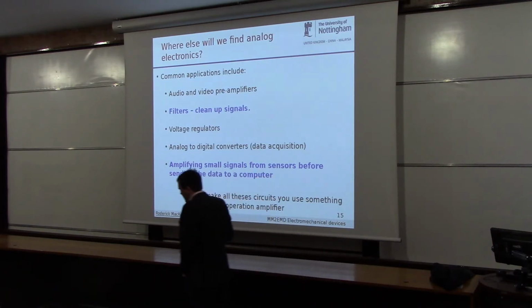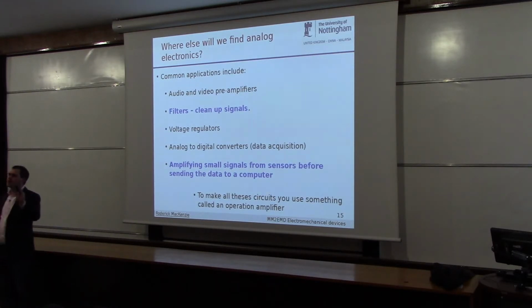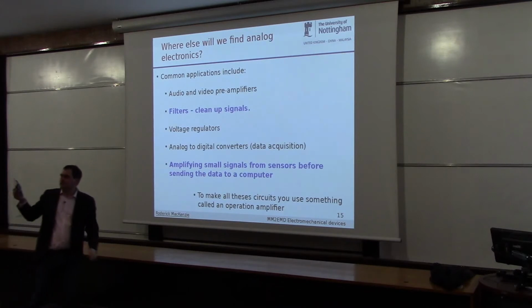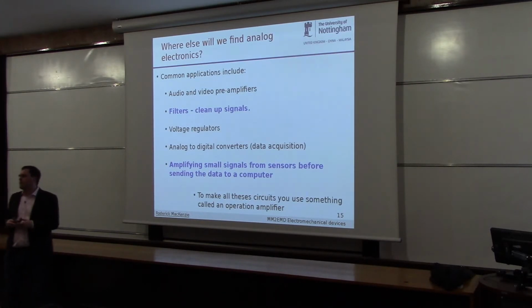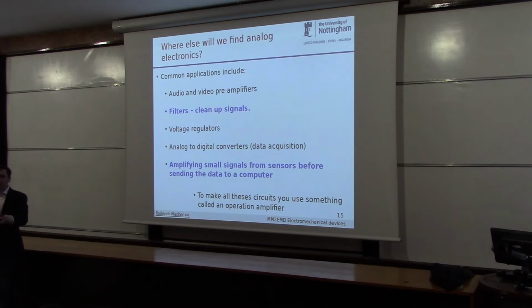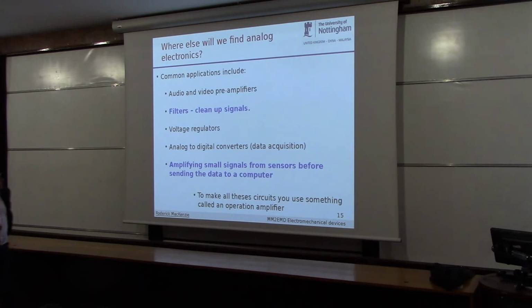So for example, on this thing, it's got a couple of batteries in it, and it's got some digital transmitter in it. The power the digital transmitter will want may be like 3.2 volts, and the voltage the batteries supply will be maybe 5 volts or something. So there'll be some analog piece of equipment in here that is regulating the power the batteries supply to the digital circuits to make sure those digital circuits always have the right voltage. And as the voltage in the battery goes down over time through the lecture, these analog circuits will adjust the supply voltage to the digital circuits.